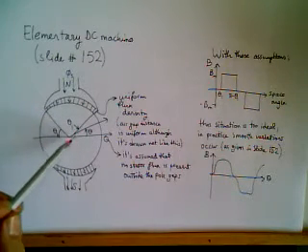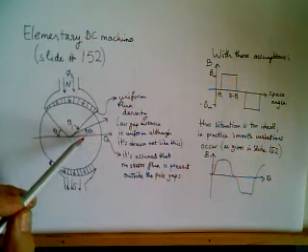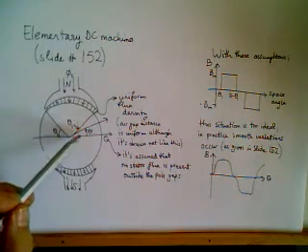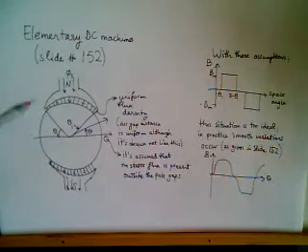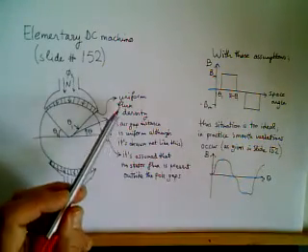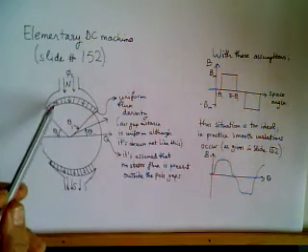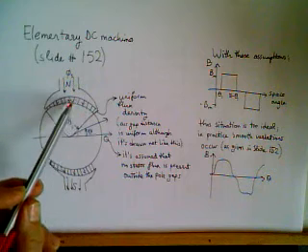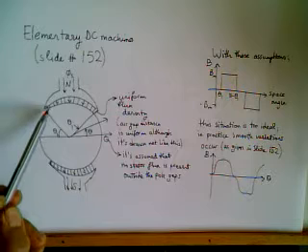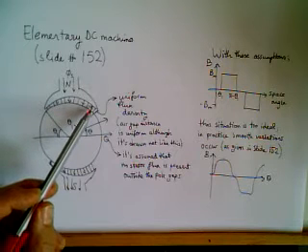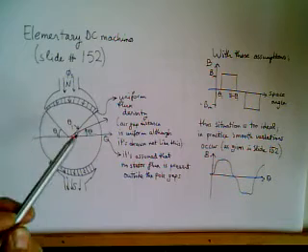So the axes are defined such that theta is the azimuth between the so-called orthogonal axis with respect to the flux, etc. And since flux should be uniform, the air gap should also be uniform, but this drawing is not perfect, so it seems as if the gap distance is larger compared to that side, which is not the case in real machines.